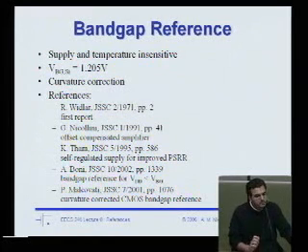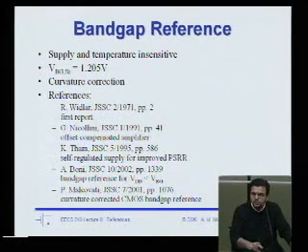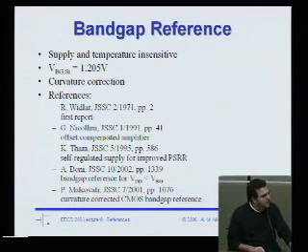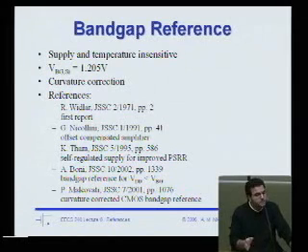Okay, and then probably, I'm guessing, when Widlar or whoever first designed this circuit, and they tested it and it worked, felt pretty good about it, and they realized that the voltage they got out was about 1.2 volts. Okay, at the end of the day, when they multiplied a constant times kT over q and added it to a VBE, and then they started thinking, hey, that's kind of close to the band gap, right? And so then they did some analysis, right? They wrote down some equations, and lo and behold, at the end of the calculation, wow, they produced a band gap voltage, which probably was an accident.